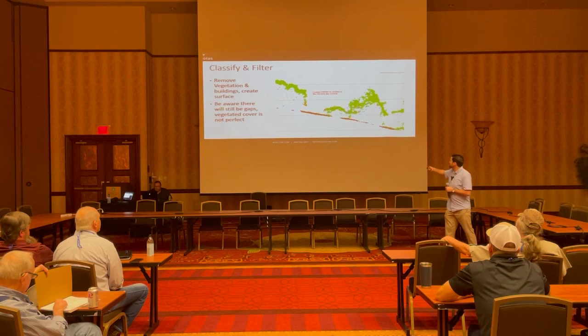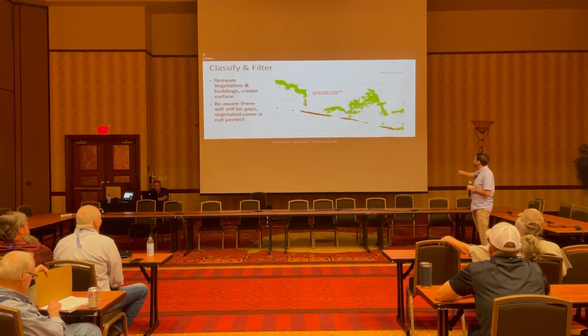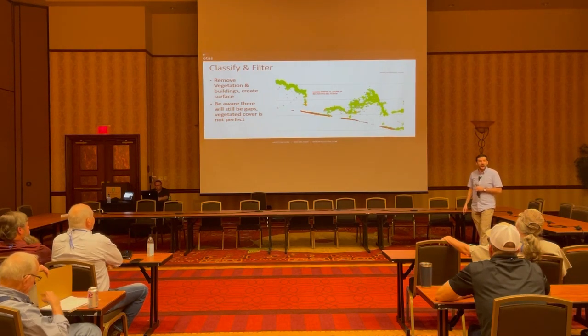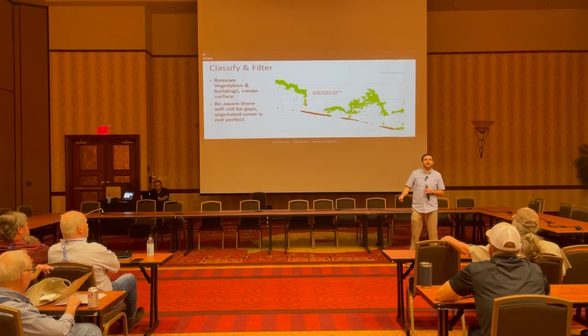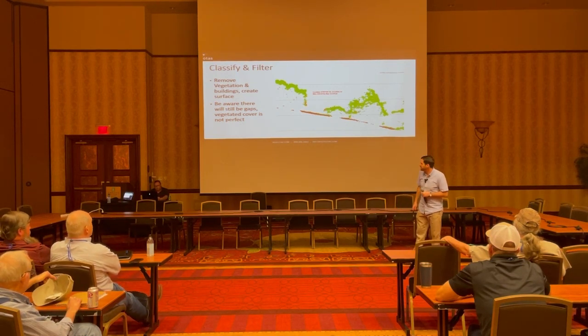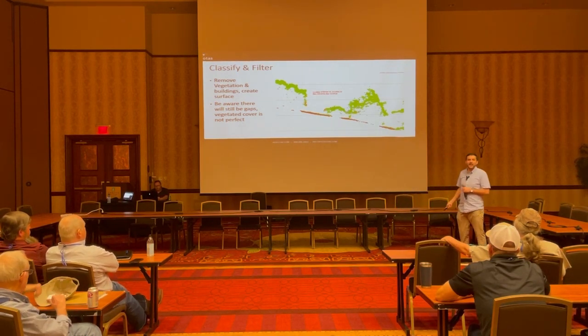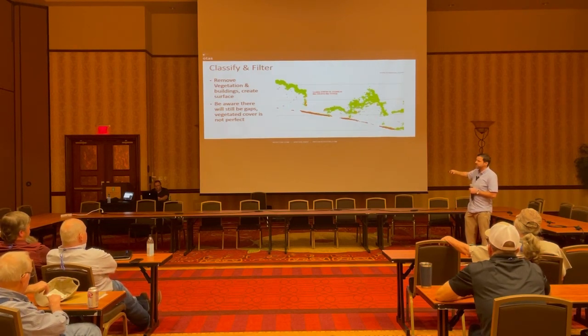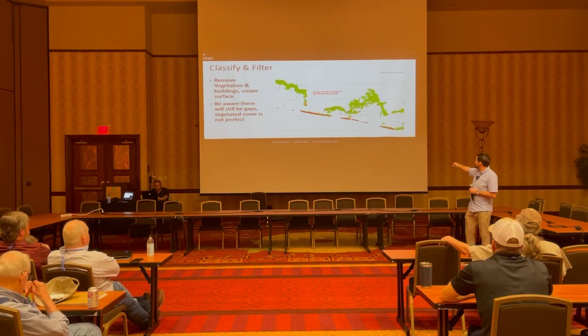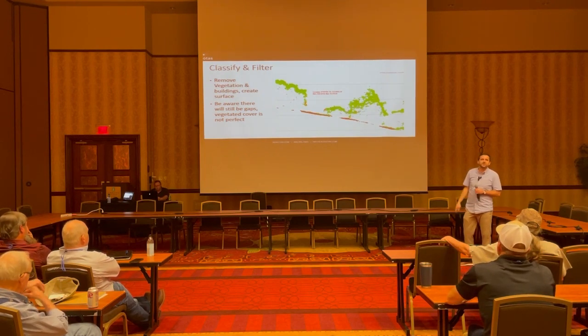But you'll also notice there are still gaps. There's gaps in all data. None of this data is perfect. No, there is no LiDAR unit, by the way, that can penetrate all vegetation perfectly and just get you the ground. There is absolutely dense enough foliage out there, especially with all kinds of vines or really dense tree cover in the summer months, that LiDAR is not going to be able to penetrate. Make sure you're aware of that because once again, this is one of those things any human can look at this and easily interpolate and say, yeah, there's a surface under there.